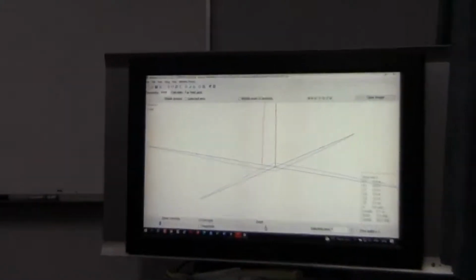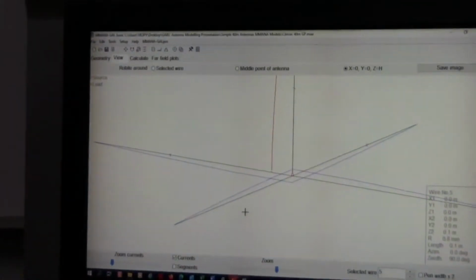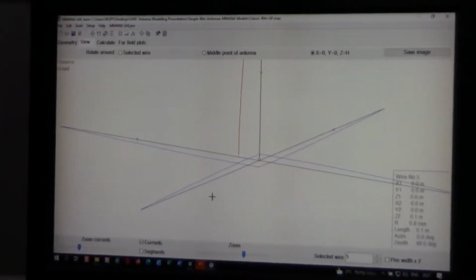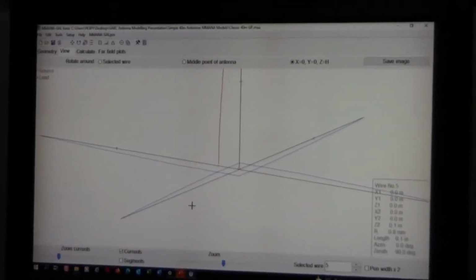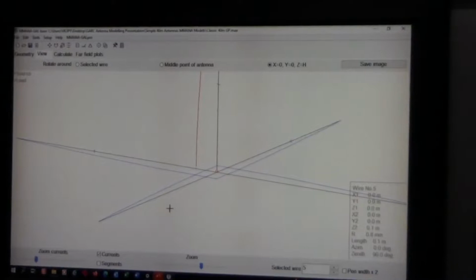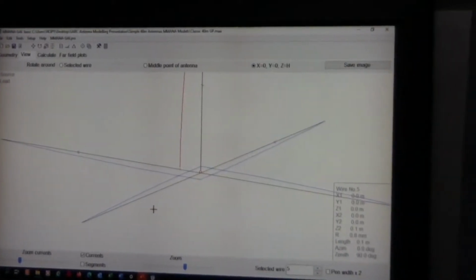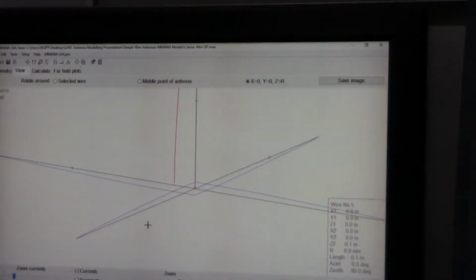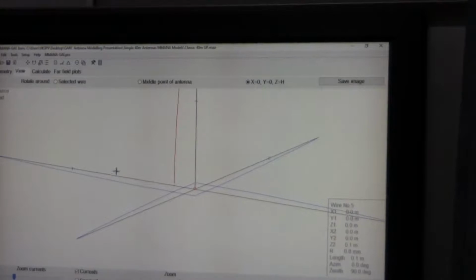Another point to look at is the blue bit. Red shows the vertical current, so that's responsible for the vertical radiation pattern of the antenna. Blue shows the current distribution in the radials, and they're horizontal wires, so that would give rise to horizontal radiation, and up close to the radials you would actually detect a horizontal electric field. But an interesting thing, if you look at the diagonally opposite radials, you see the current in this radial here, it shows the blue line under the wire, and on this one, it's above the wire.